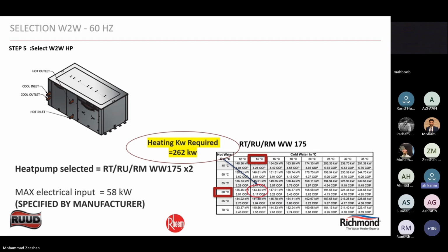We have mentioned the sizing of the heating coil for both the hot water and the cold water, but we didn't take into consideration the weather conditions. In winter, we have a cold range and a normal range. So at which condition have you sized? I've considered the colder side in some of the places. If you have a colder region, let's say 5 or 10 degrees, like Abha, then the selection will again be tailor-made for such conditions. But for my example, I chose 15 degrees as ambient.